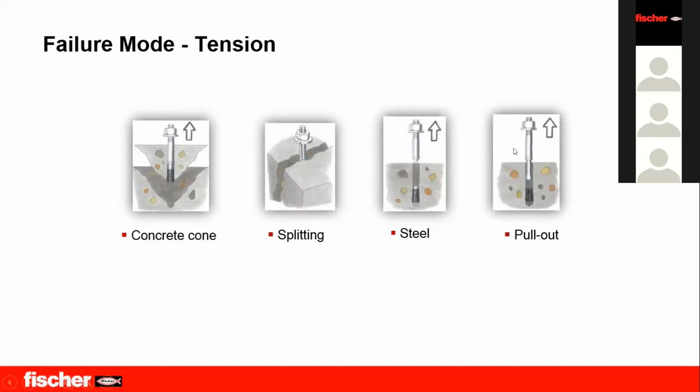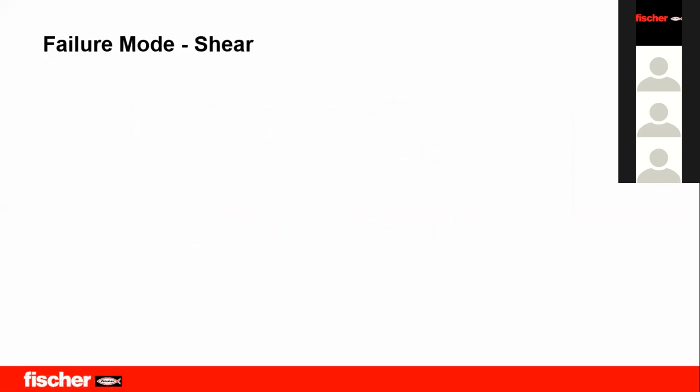The anchor doesn't have a proper adhesive bond between the anchor and the chemical, and this is what the fifth factor, the cleaning, was about. The cleaning should be done properly to make the adhesive bond very high quality between the anchor and the chemical, and between the chemical and the concrete itself.